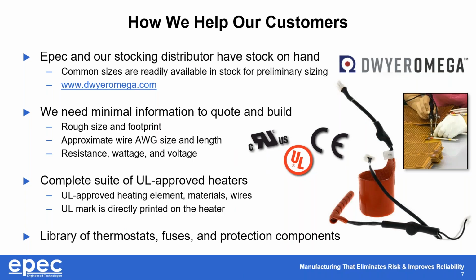Additionally, if your application requires some kind of UL or CSA testing, we have numerous existing stack-ups and designs that have the existing UL and CSA mark, meaning you can avoid tens or hundreds of thousands of dollars and weeks or months of timeline if you do need a UL mark. The challenge there is you are limited with some of the cross sections and some of the material thicknesses. If you're willing to work with us, there should be a solution that we can offer you if you do need a UL mark.